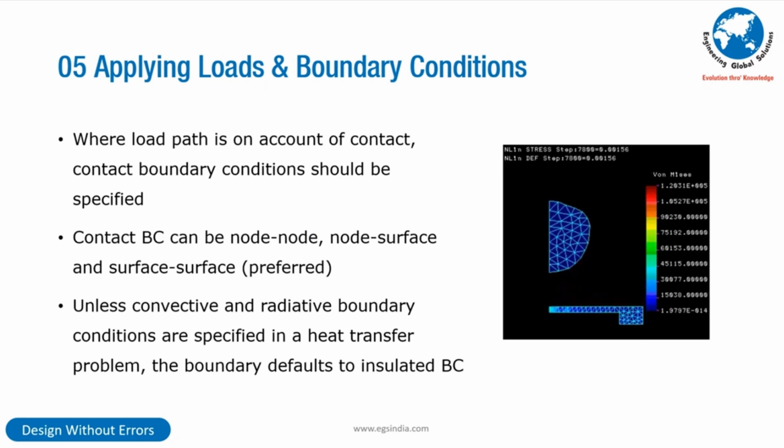Use it for helmet impact analysis, tire impact analysis, so many different places. Energy principle. This is what we need to bring in. And the contact has to be established. Contact boundary conditions have to be very clearly defined: node to node, node to surface, or surface to surface, which is preferred.